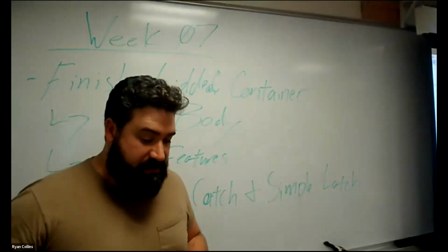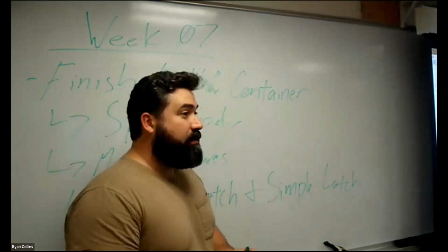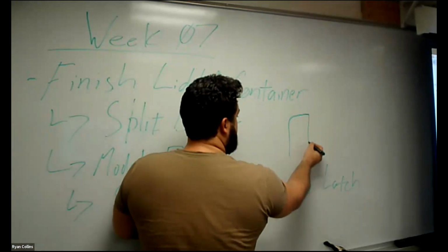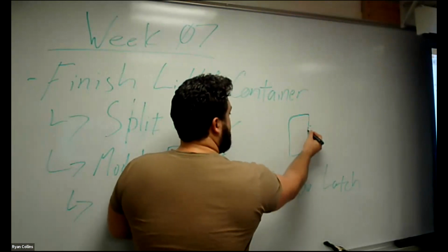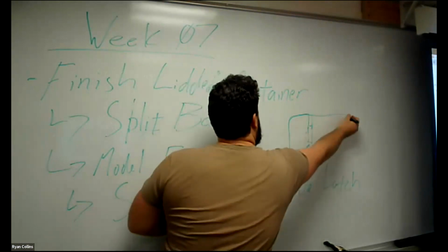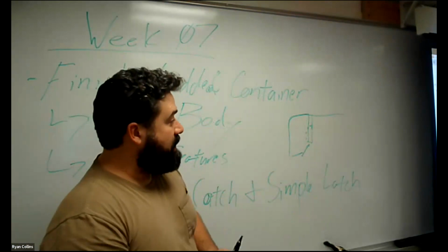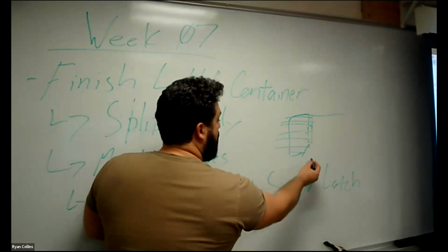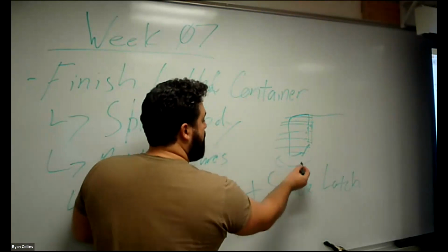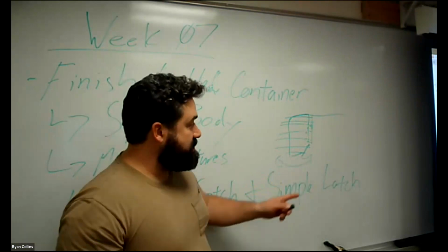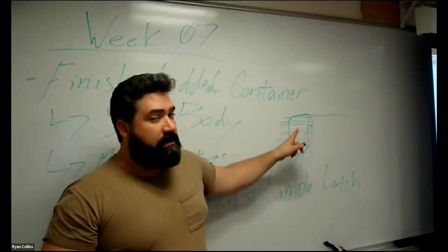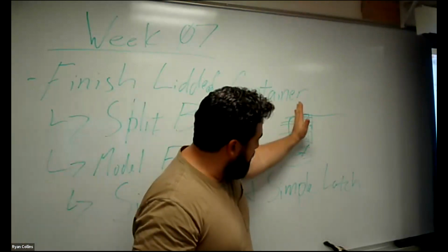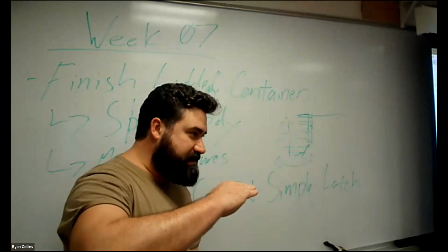stop sharing so I can show on the board here. Remember that, yes, that latch would be printed, and I'm just showing it like it's upside down. Got the little thing, and then there's that little bump between the two halves. Great. But ultimately, that is going to be printed sliced. And you are asking this thing to move slightly in those directions. So it potentially can crack your prints. Now, if you make that catch a little bit thinner, you might get a little more flex out of it.